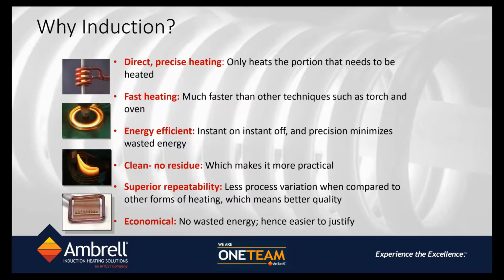And usually, like in an oven or a furnace, the entire part tends to heat. So when you have applications where you need to heat the entire part, then of course induction and ovens do the same type of job. But if you're looking to just heat a localized part or a localized section on a part, induction is superior in terms of its ability to deliver heat in a small area.